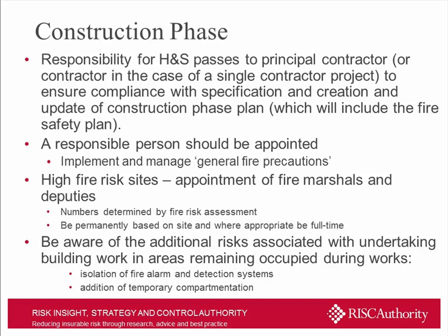Where we have high fire risk sites, and again I'll come on to what that might mean in a few moments, there's a requirement for the appointment of fire marshals and deputies. Their numbers are to be determined by fire risk assessment, and wherever possible, they should be permanently based on site and full time. And they have specific roles and responsibilities for ensuring that certain routine checks are undertaken on a daily, weekly, monthly basis, and that there's recording and reporting of problems that might exist, to ensure that fire safety is as effectively managed as it possibly could be.